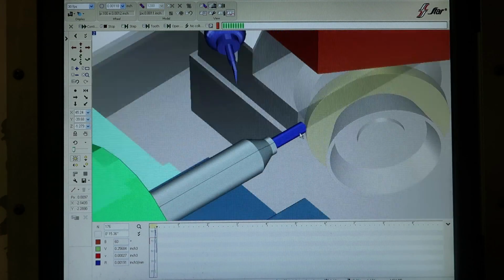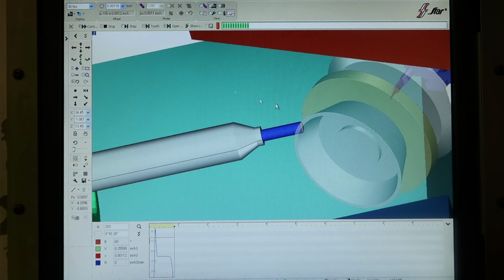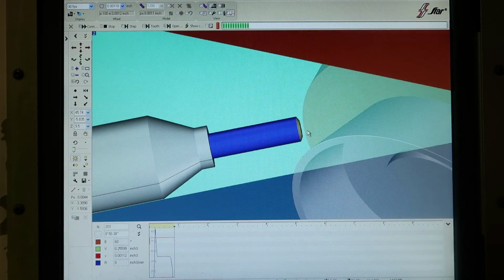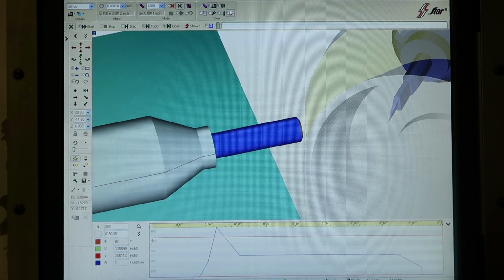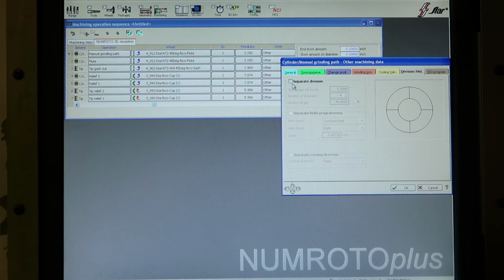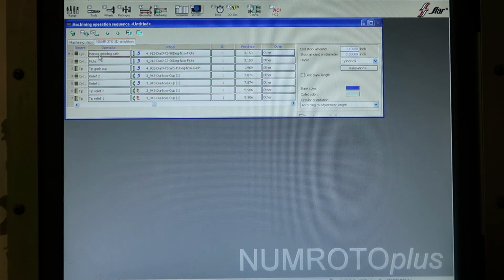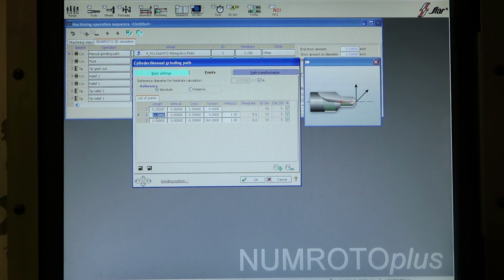I'm going to step over to this, see we're not too bad off. Let's step through it and see. But our chamfer isn't big enough, and also we're doing this at every flute. We only need to do it once. So we've got to go over to here and select this division. We're doing only one division instead of 4 flutes because we're rotating 360. So we've got to do that. And this, let's go 0.070. We'll try that and see if that works.